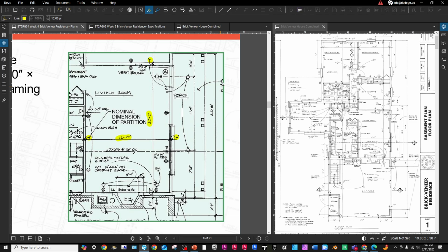So lumber shrinks after being seasoned or air dried in a kiln drying. And the surfacing at the planing mill is going to further reduce its measurement to its nominal size once it's located and sent to your local Home Depot or Lowe's, used for commercially, right? Actual versus nominal.